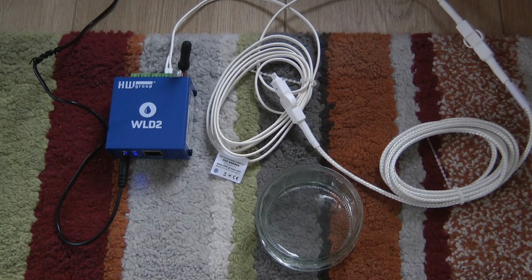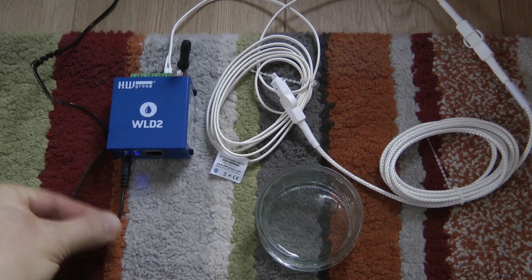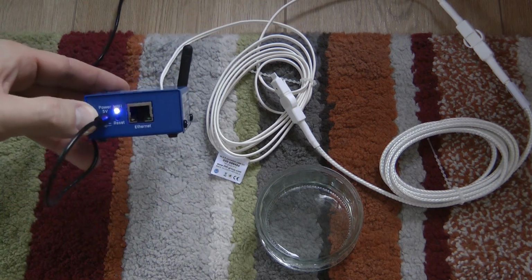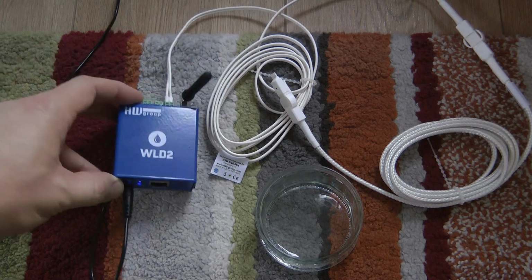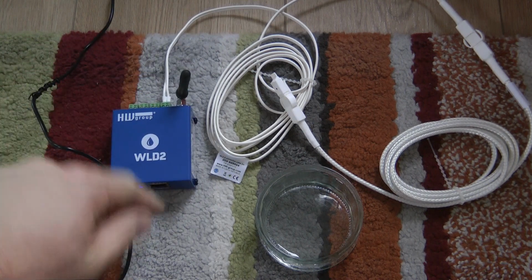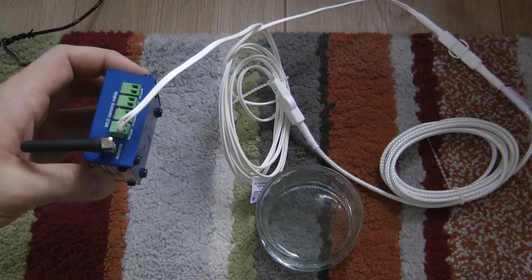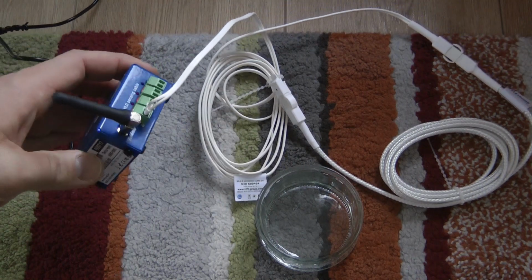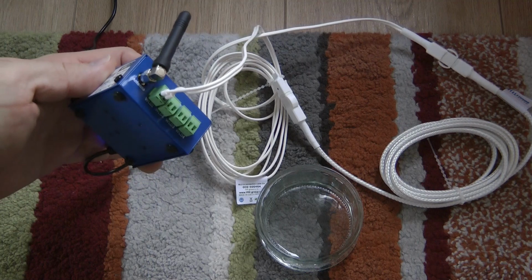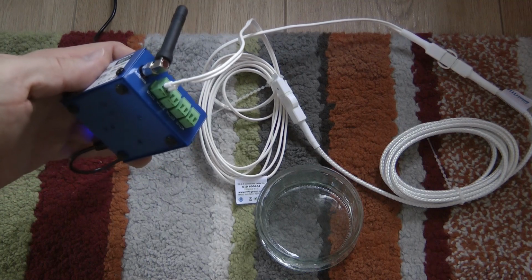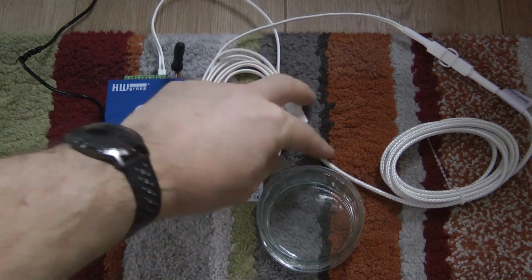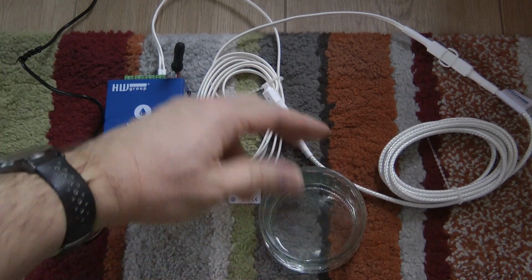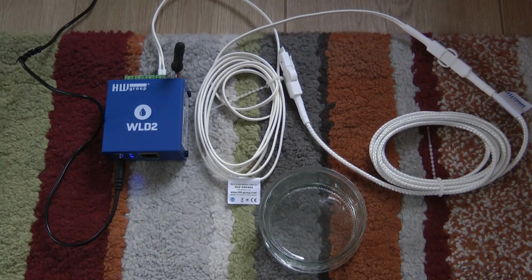As you can see, I set up the DLW. I use the external 5-volt power supply. So it is connected, and I have a blue status LED on the Wi-Fi. Obviously, I'm using it on Wi-Fi. I haven't connected the Ethernet cable. And on the back, I have connected the water sensor, or the leak sensor, to the first input. The second, third, and fourth inputs are not connected at the moment. And I have the sensor here, and I have a cup with some water in it. So this is how we are going to test the water leak detection, or the flood detection.